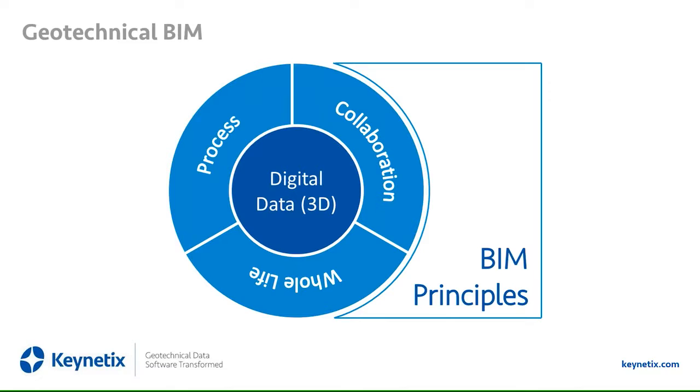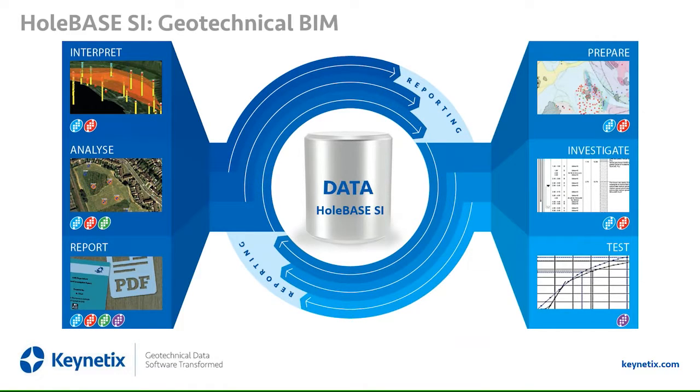So I'm not going to go into great detail in here, I'm just going to jump into the software and start showing you. But for us to do a lot of geotechnical BIM, we use our product called HoleBASE Si. So you've got the central core of data, and if you've got that data in this central core, then you can use it. Perhaps you can use existing projects. You can look at when you've got a new job appearing in a new area. You can look at existing data. You can look at GIS maps. You can pull the whole information together to help you refine your site investigation. Where are you going to put your boreholes? Where best to drill them? You're not starting from scratch. You're building on existing knowledge when you come to do that, if you've got the data in your central database.